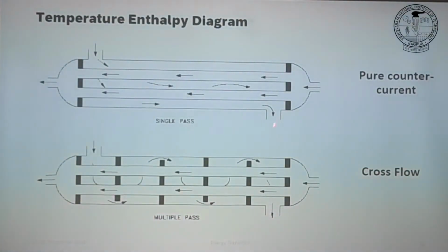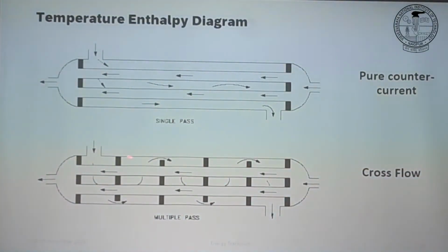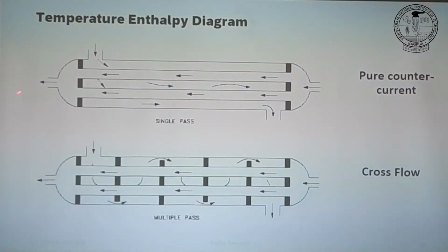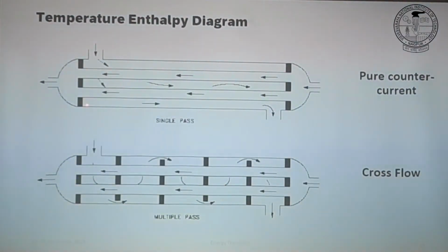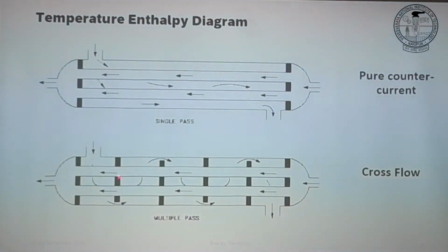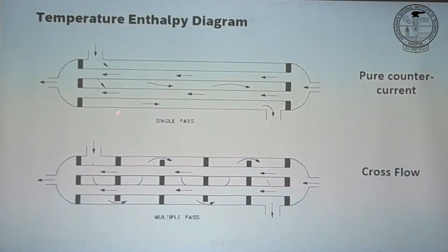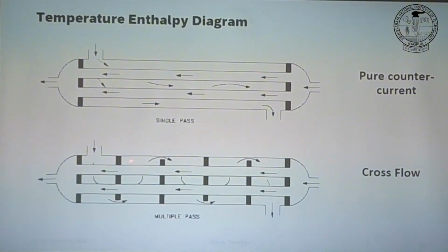So what is the impact of going from here to here? From here to here, the pressure drop was low. But suddenly, your flow length was only this, and delta P is 4fLV squared over 2gcD. 4fL, your length is this much. But what we did here, we increased the flow length. The flow area was the cross-sectional area here minus the tube area, but here the cross-sectional area is only this, so in this direction, you increase the velocity, right?